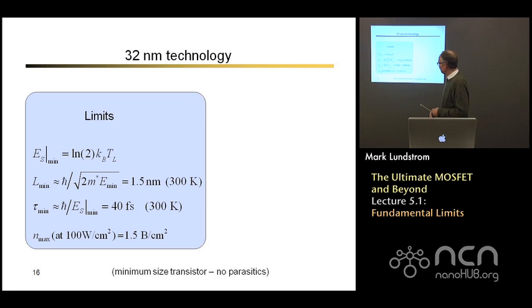That's really fast. We could say if the area of a transistor is proportional to the minimum channel length squared, we could produce a density of transistors that would be enormous and sort of unrealistically high. Another way to get a density of transistors that's more reasonable is to say how much power dissipation on a chip can I cool at reasonable rates and at reasonable expense.